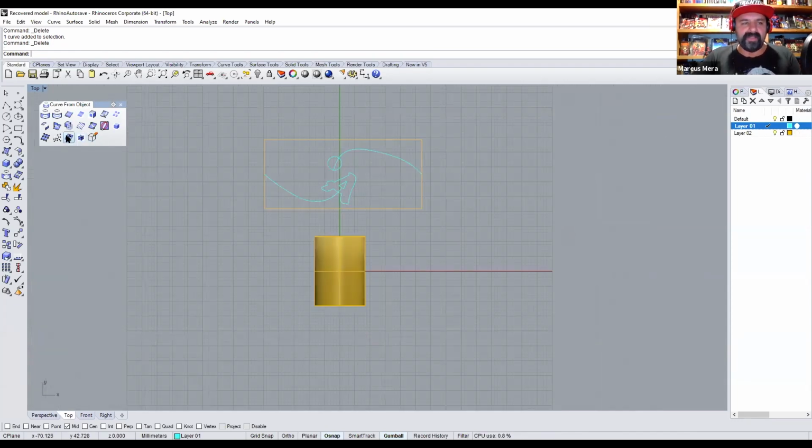Now we're going to come back to that UV command. You have your palette open. It's hovering over here because you're going to use it again. We're going to select everything with a left click drag, right to left, and select. And I'm going to hit the control button and left click to deselect the outer box because we don't need that. And we're going to come over to the UV command. To create the UV is left click. To apply it is right click.